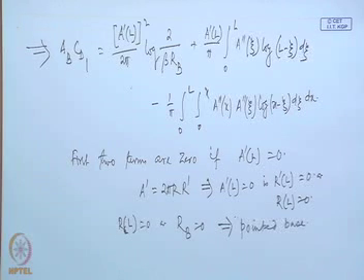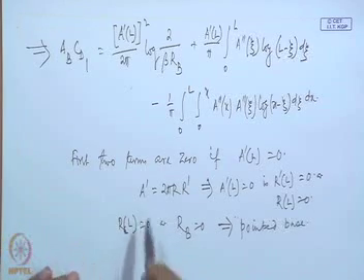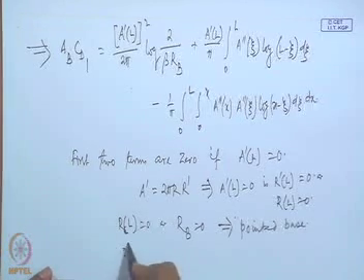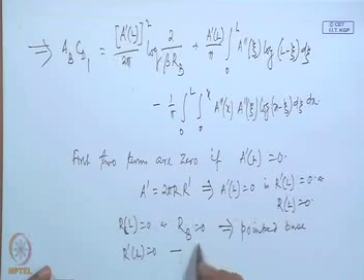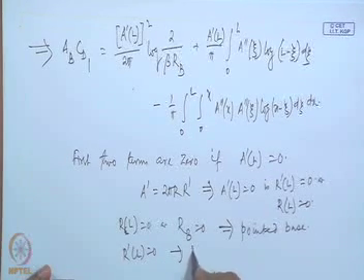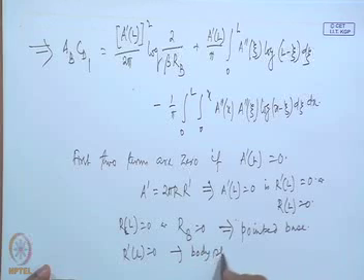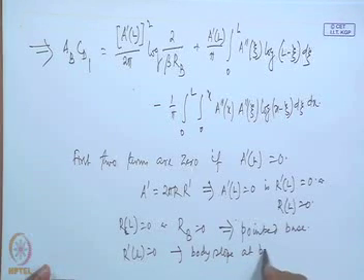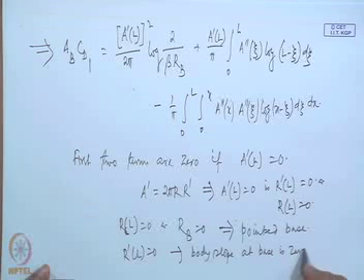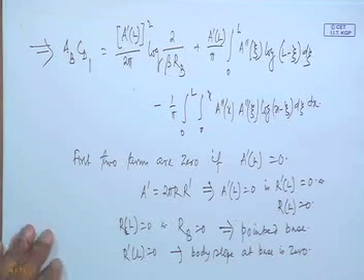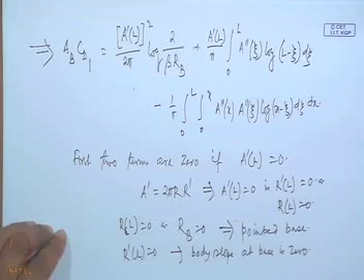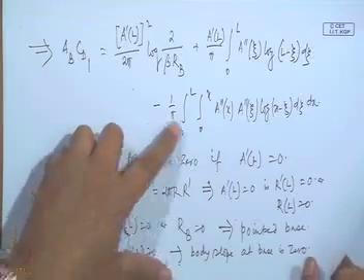So, if the base of the body is also pointed, then the first two terms also become 0. Or if r prime L equal to 0, then the body slope at base is 0. So, if the base is also pointed or the body slope at the base is 0, then the drag is given by the last term.